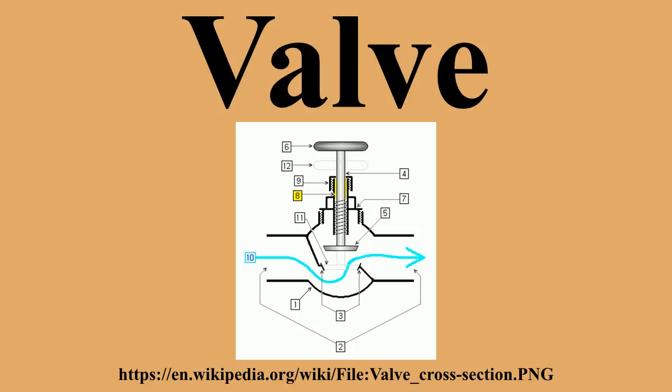During manufacture of the valve, the internal parts are put into the body and then the bonnet is attached to hold everything together inside. To access internal parts of a valve, a user would take off the bonnet, usually for maintenance. Many valves do not have bonnets. For example, plug valves usually do not have bonnets. Many ball valves do not have bonnets since the valve body is put together in a different style, such as being screwed together at the middle of the valve body.